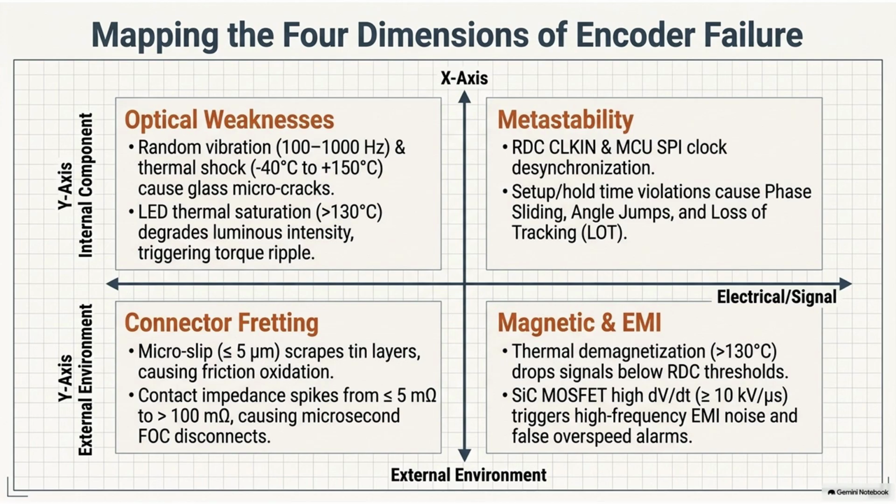It's like, okay, imagine trying to read a book with a tiny flashlight while someone next to you is blasting a massive high-intensity strobe light at random intervals. That's a perfect analogy. Right. The strobe light is the EMI from the transistors. The flashlight is your magnetic encoder signal. The signal is completely drowned out, which causes the RDC chip to register these erratic voltage spikes as actual encoder pulses. And the system registers these false pulses and instantly miscalculates the speed. Which triggers a false overspeed alarm. Right. It panics because the electrical noise is mimicking a motor spinning out of control.